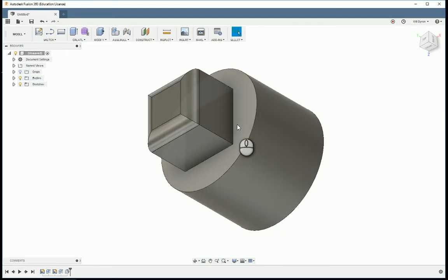Typically speaking, whenever you're making parts fit together, from a 3D printing standpoint, it's always better to have a rounded edge. The printers that we'll have access to aren't going to be accurate enough that you put something at 1 inch wide, you make a hole that it's supposed to seat into at 1 inch wide, and it fits. It's not going to fit. If you leave a little bit of that rounded edge, there's a potential that it can slide in, and if nothing else, it's going to make lining it up easier instead of trying to do a 1 inch square hole. Just something to be warned about.